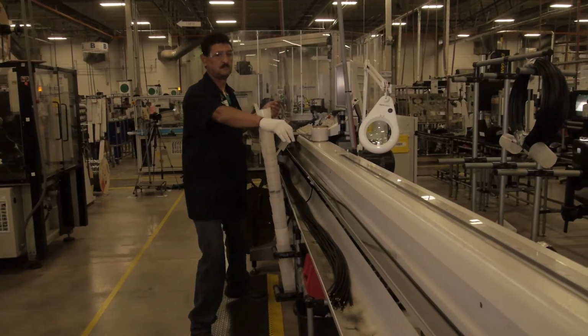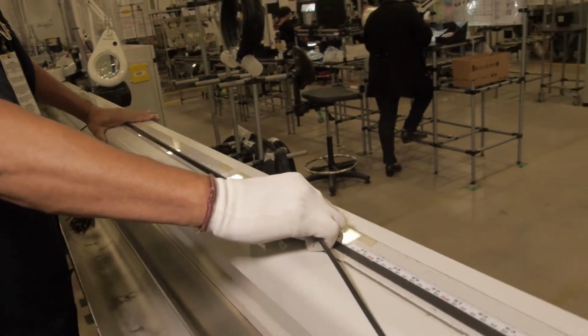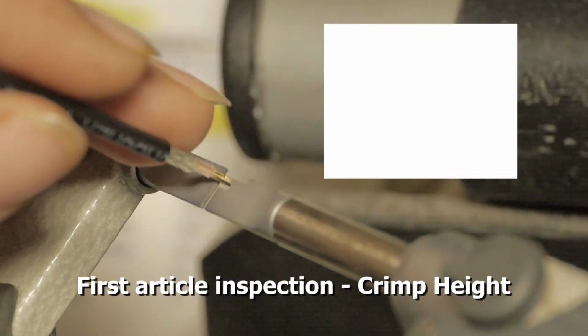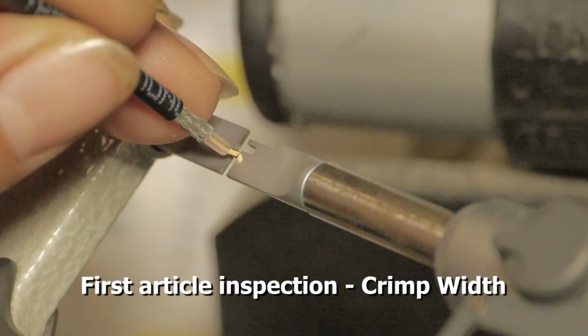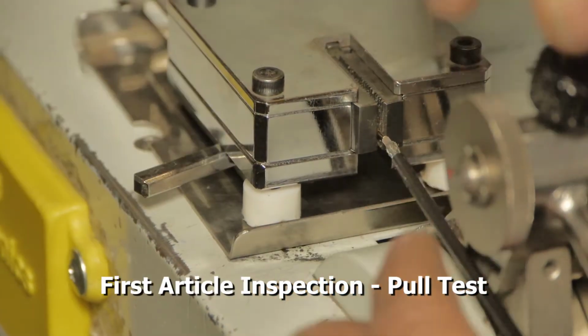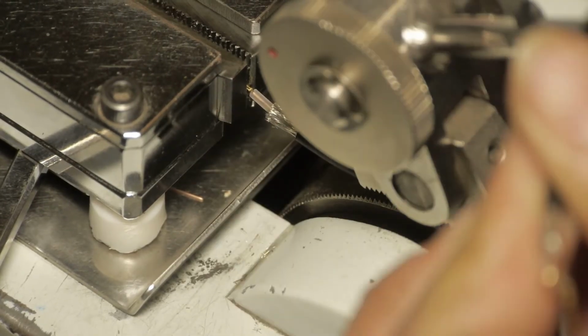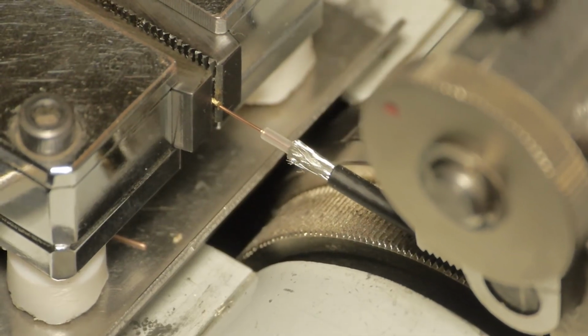Once the first few pieces are processed, first article inspection should be carried out before proceeding further. First article inspection includes verifying the length of the cable, verifying the core crimp height, verifying the core crimp width, verifying crimp pull force. First article inspection ensures the quality requirements are met and prevents producing non-conforming products and scrap.